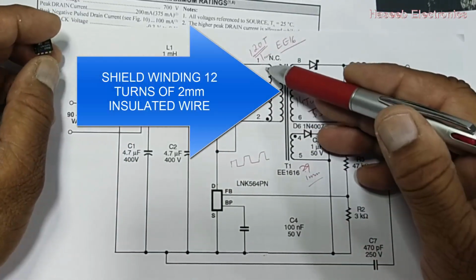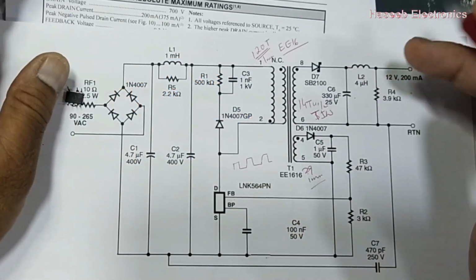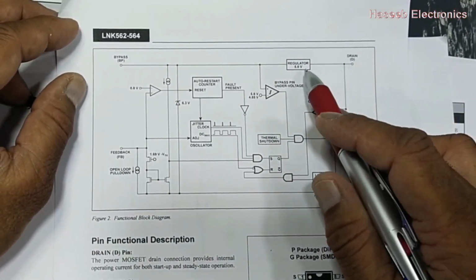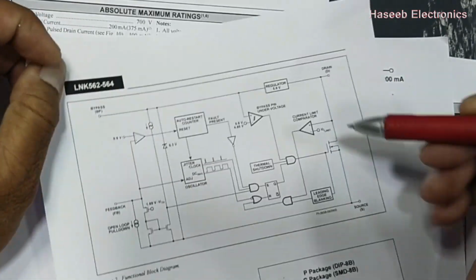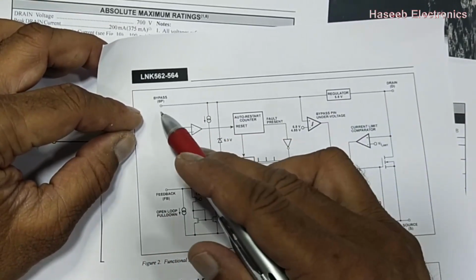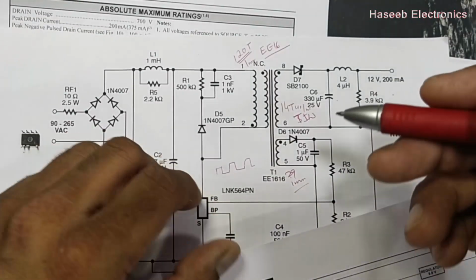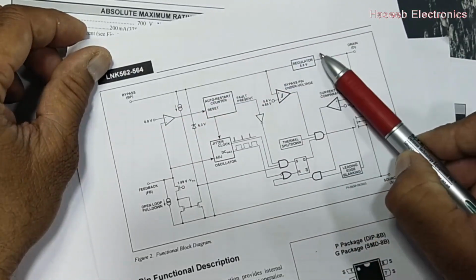When we apply voltage, it will charge internally through its 5.8 volt internal regulator, because it does not have any external charging circuit, external startup circuit. So it will receive voltage from this winding, positive voltage from here, and it will charge this bypass capacitor. That is outside. We can say it is working as a VCC capacitor. It is a 100 nanofarad 50 volt capacitor. When it receives 5.8 volt, this IC will start switching.